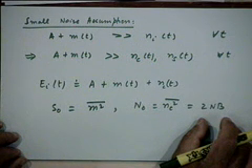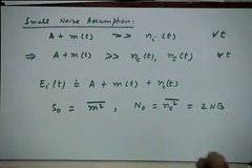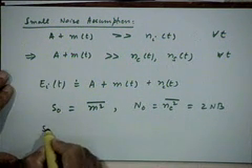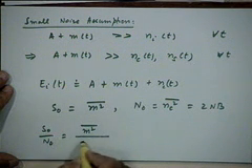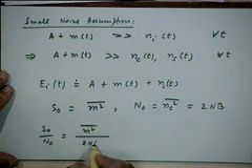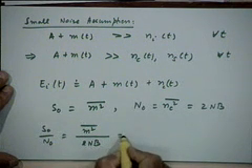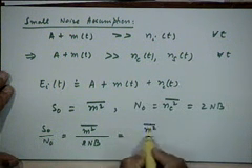Remember, this is an AM signal whose bandwidth is 2B, from Fc minus B to Fc plus B. So, N by 2 into 2B is NB, the corresponding negative part is NB, so the total output noise power is 2NB. So, same picture as before, therefore S naught by N naught. Nothing has changed, things are absolutely the same as before. You can write this as m square bar upon